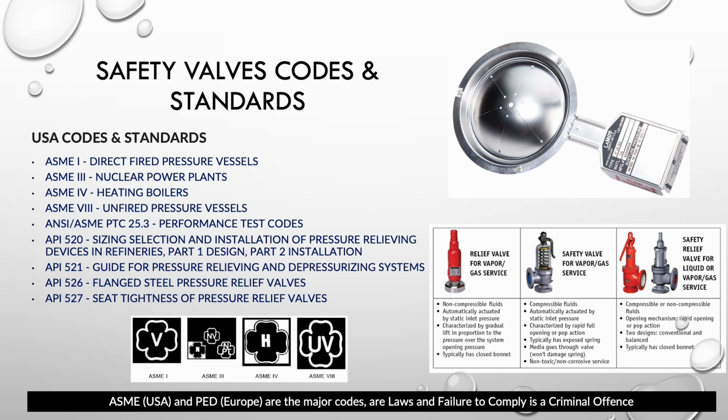Now the ASME part is going to deal with what type of pressurization scenarios, what type of parameters you're going to need to put in your equation to actually start sizing those relief valves. So if you're dealing with a heater, a fire, like a direct fired heater, like a furnace, that means if you have a relief valve there, you're going to have to go to ASME 8. It's literally self-explaining.